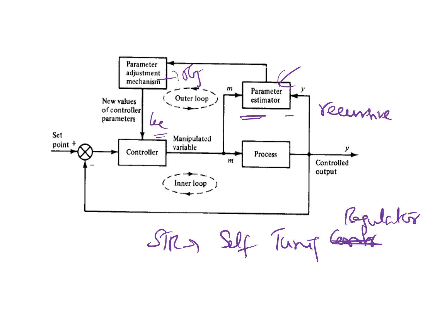Okay, so this parameter, for example, if the transfer function is e power minus TDS approximated value, so tau s plus 1. Then what we do is, then using the measured values of the manipulated variable, so from this we know the manipulated variable and we know the controlled variable, this control output. Estimate the values of parameters. So you have to estimate what is KP, what is TD, and what is tau. Estimate these parameters and employ.